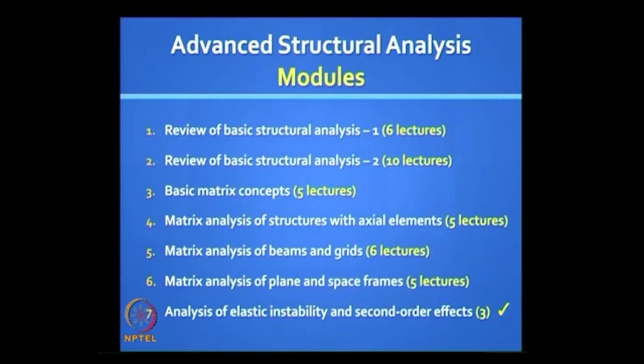Then we looked at ways of finding displacements, deflections in trusses, deflections in beams, rotations, curvatures in beams and frames. We did this by many methods, but we found that the most powerful and general method is the principle of virtual work. And then we looked at other energy theorems which could handle both statics problems and kinematics problems, and they had their equivalent work theorems. You had the principle of virtual displacements, principle of virtual forces.